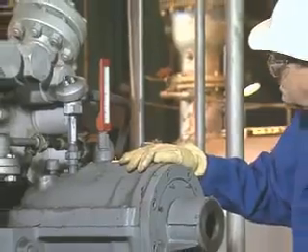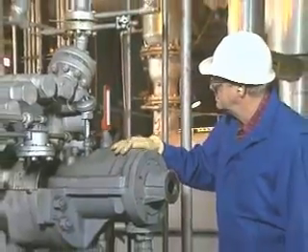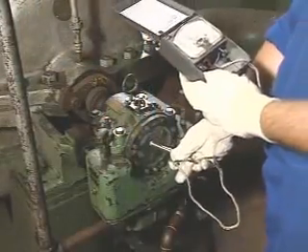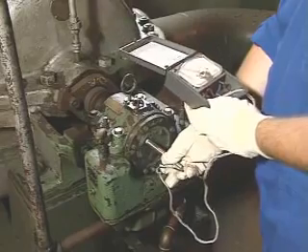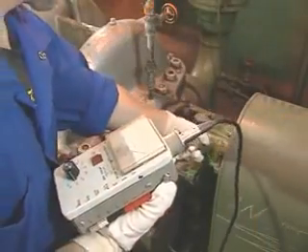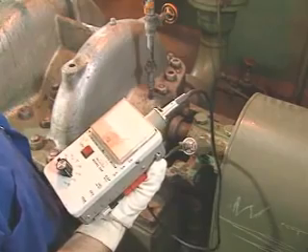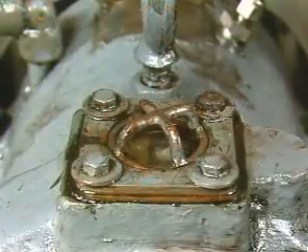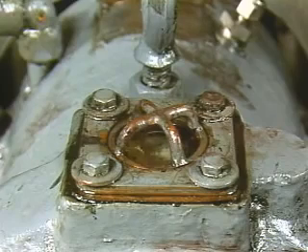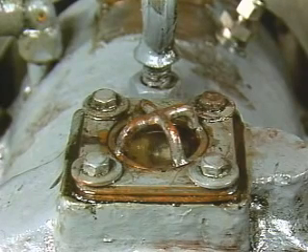One way to check for overheating or excessive vibration is by touching the bearing housing. You can also use an instrument called a pyrometer to measure the temperature at the bearing housing, and a vibration meter to measure the amount of vibration. To check the flow, level, and condition of the lubricant, sight glasses are commonly used.